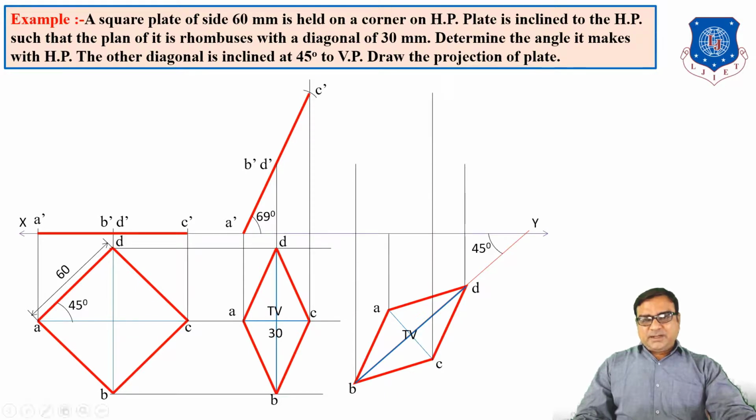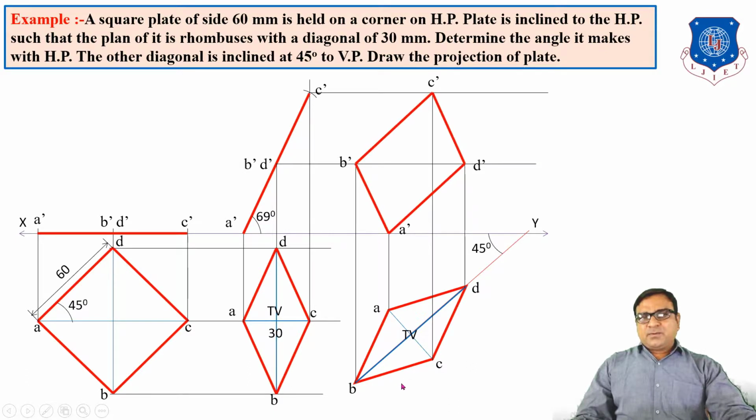Now draw vertical projection lines and horizontal lines from the front view. The intersection points A, B, C, D and A dash, B dash, C dash, D dash will be obtained here. A dash, B dash, C dash, D dash. Join all points, and you will get one parallelogram, meaning the front view of the plane.